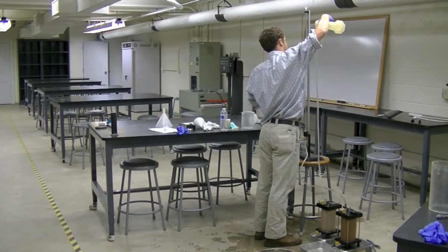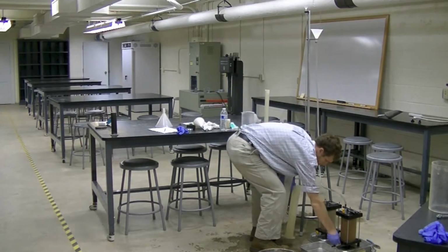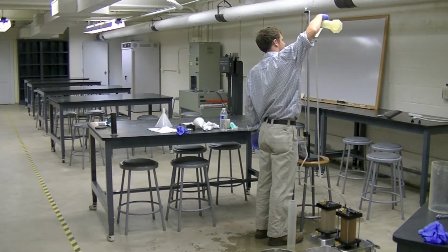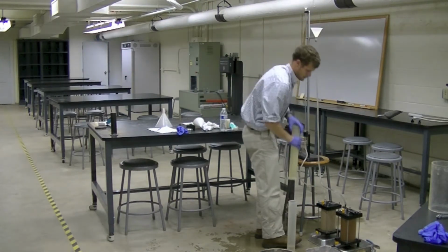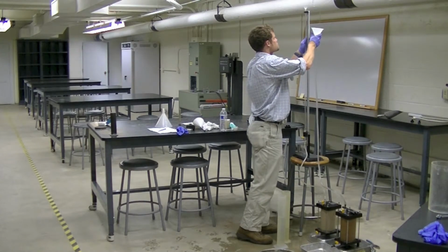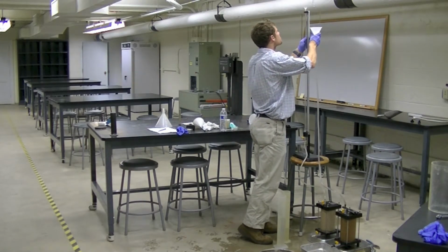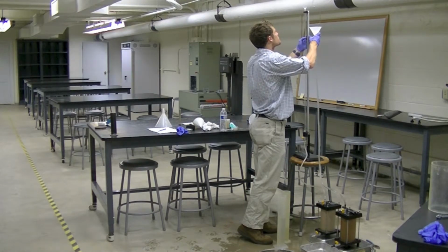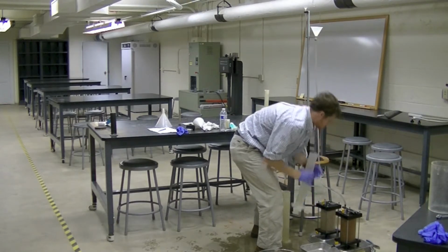We will first begin with the constant head test, which consists of coarse-grained material. Open the outlet valve and allow water to discharge. Keep adding water to the funnel until the flow is constant. Stop the flow. Set the funnel, i.e. hydraulic head, at the desired height for the first trial. Record the total head difference. Place a pan or beaker beneath the outlet so that all the discharge may be measured.